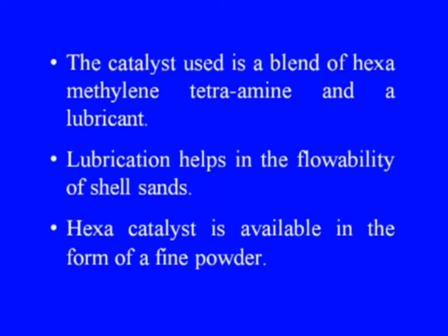The catalyst used is a blend of hexamethylene tetramine and a lubricant. Lubrication helps in the flowability of shell sands. Hexa catalyst is available in the form of a fine powder.